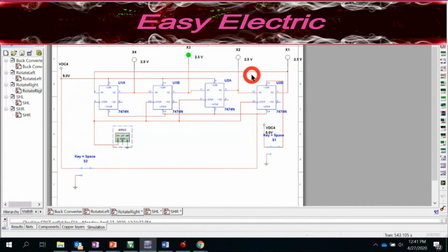shift register, right? Because if all of them are zero and you have shift right with the rotation, you definitely couldn't see anything on these LEDs, right? That's the reason I connect to this. Just for a short time I put that zero, make a one, then deactivate that. Then I will see how that one rotates inside this shift register. That's the only difference from the original design.